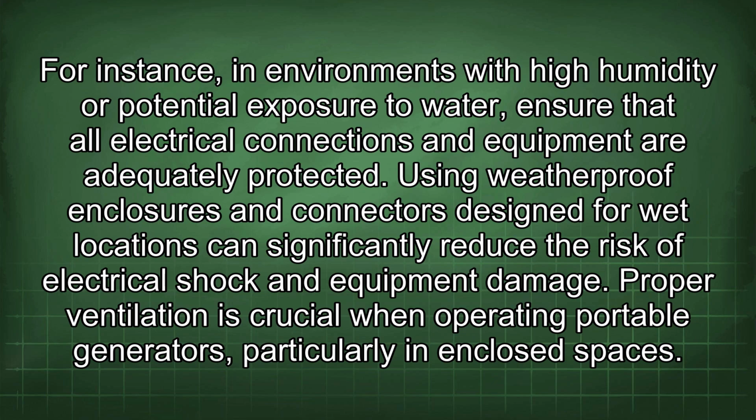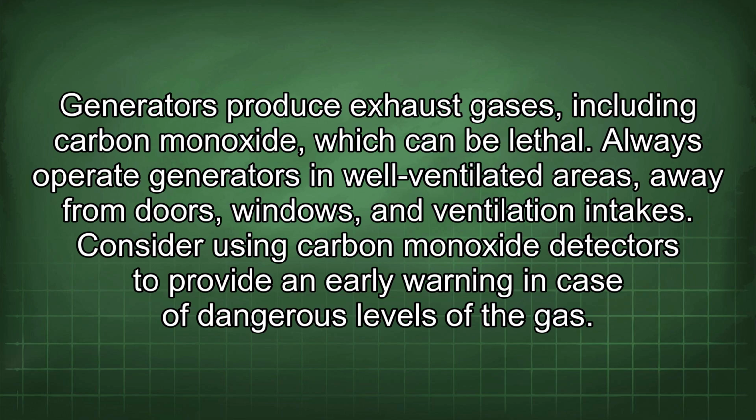Proper ventilation is crucial when operating portable generators, particularly in enclosed spaces. Generators produce exhaust gases, including carbon monoxide, which can be lethal. Always operate generators in well-ventilated areas away from doors, windows, and ventilation intakes. Consider using carbon monoxide detectors to provide an early warning in case of dangerous levels of the gas.